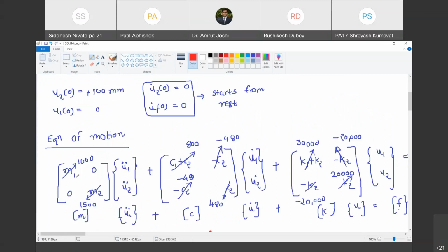For example, you may imagine a load-bearing system where we consider wall as a part of structural element. So the mass is not only distributed at floor level, it is not only lumped at floor level, it's also distributed along the wall.